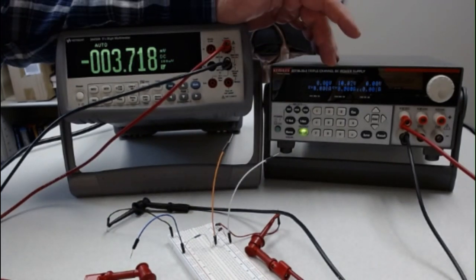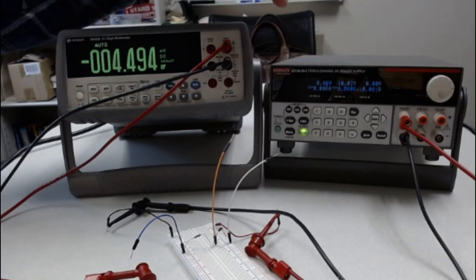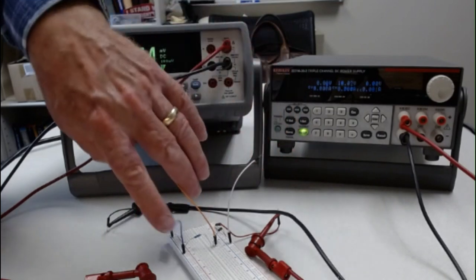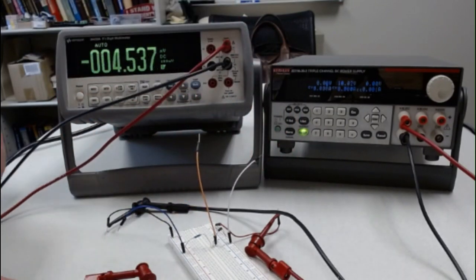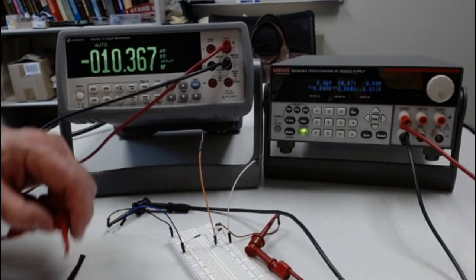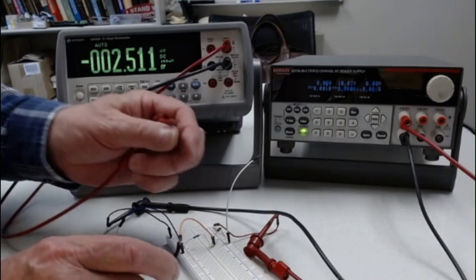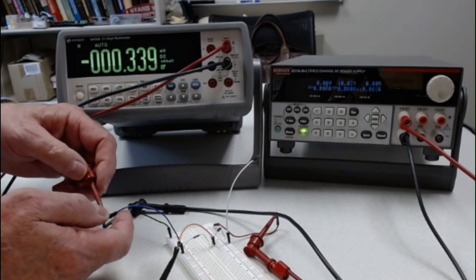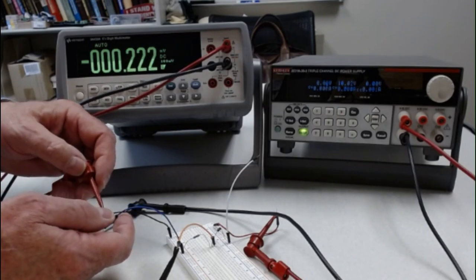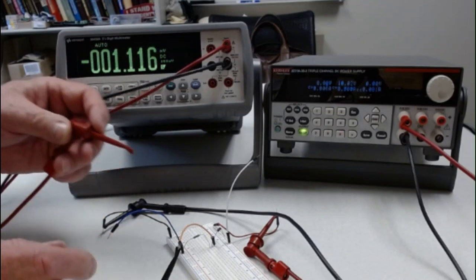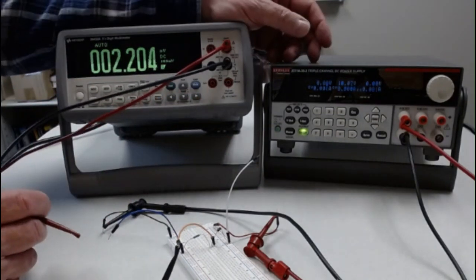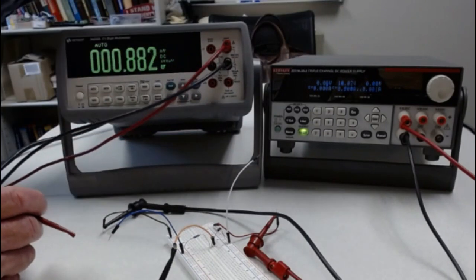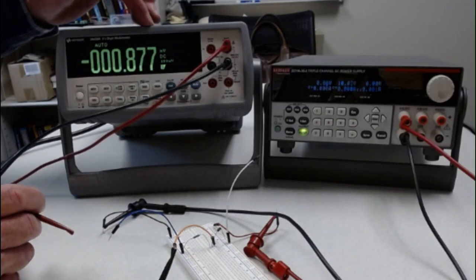So we're going to start. I'm going to go in 0.1 increments from 0 up to 1, and then 2, 3, 4, 5, 6, 7, 8, 9, and 10 volts. I'm going to read the voltage across the diode and then across the resistor at each of these points. I'm going to leave the one lead on the middle, and I'm just going to touch the other side. The reading across the resistor will be a negative, but just ignore the negative. We're going to do this as easily as possible, but yet at each station you're going to be told 0.1, 0.2, 0.3, and then the voltage across the diode and the voltage across the resistor.